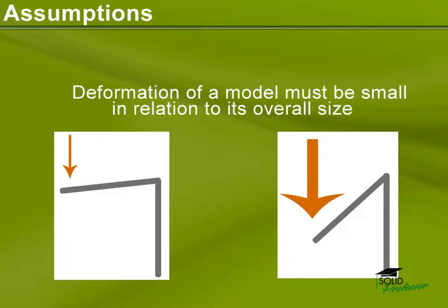A symptom of this is unexpected stiffening of the part due to deformation, much as a guitar string gets stiffer as it's stretched. If you're concerned that large deformations might be impacting your results, you may need to explore the response using full SolidWorks Simulation.